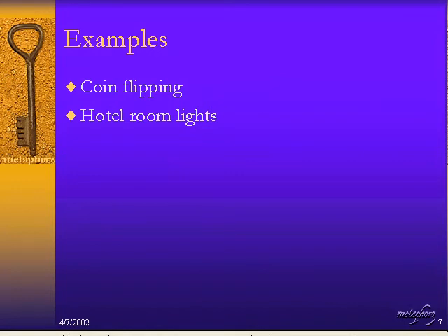Your average digital watch has controls that are really based on finite state machine execution. The main input for your watch is something we'll call the mode select, and if you have a digital watch you may very well have a button that's labeled mode. The mode switches the watch to its key supported modes such as time, alarm, timer, and chronograph.